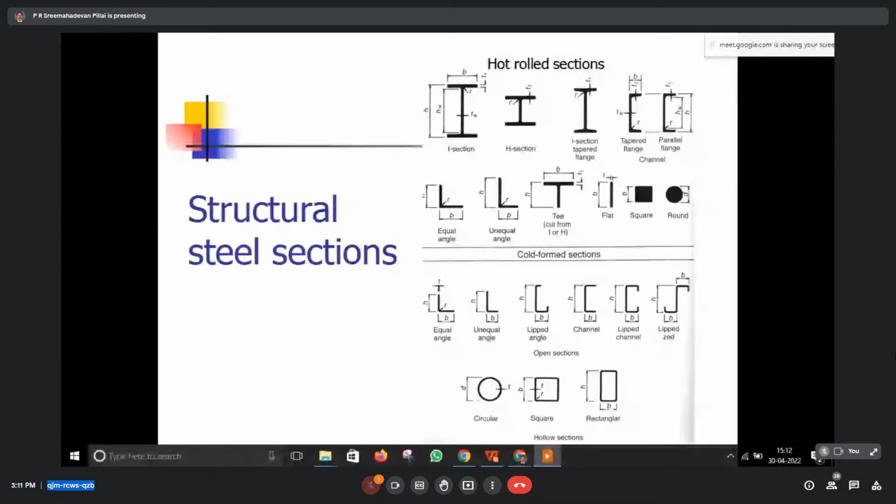So the other paper which was lying flat has bent like anything. But if it is in this shape, it doesn't bend. This is the basic theory of plate, or what is called the theory of folded plate. Similarly, instead of simply keeping the paper flat, if I bend it like an arch, the arch can be a circular arch, parabolic arch, hyperbolic arch, even a triangular arch, whichever the arch form, the arch will have a heavy load carrying capacity. That is the theory of shells.